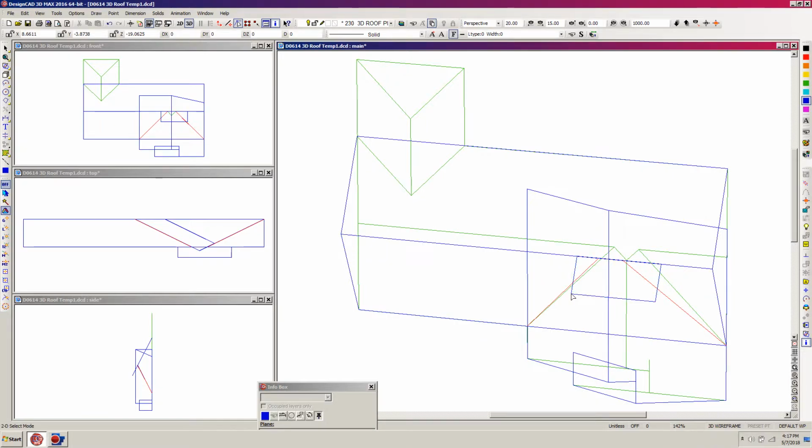And so you can see it there. And down here you can see the continuation of that plane. So that all looks good. So now I want to see where these two planes intersect with that guy. So I'm going to do a surface intersection again, and click on this plane and then this plane, and here it comes back. That should have been red. Let me go back to red here. Click on that and hit apply to selection.